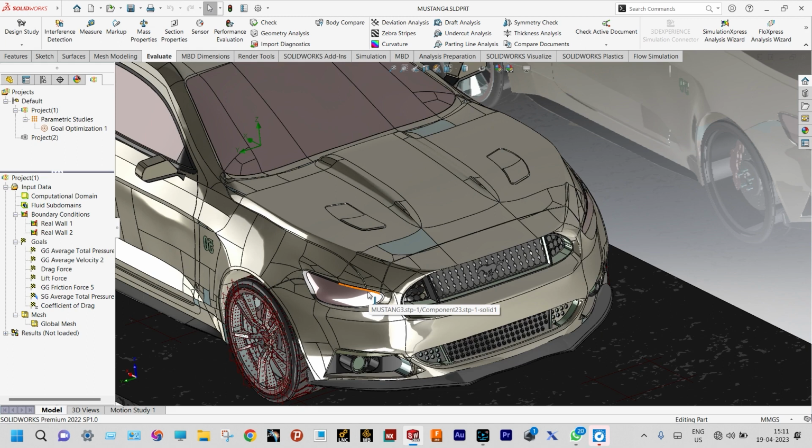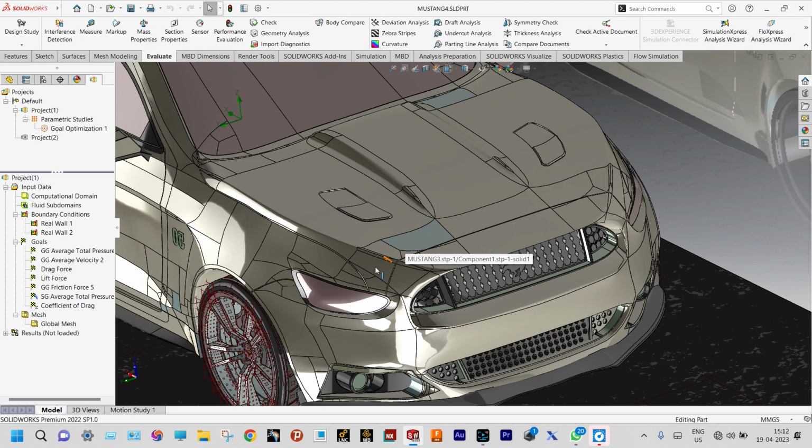Actually, in case of sports cars, the coefficient of drag is very high. Generally, in case of cars, the coefficient of drag varies from 0.2 to 0.7, and especially in case of Formula 1 cars, the drag coefficient ranges from 0.7 to 1.1. In normal cases, the coefficient of drag should be very small. Actually, this drag force depends on velocity also, right?